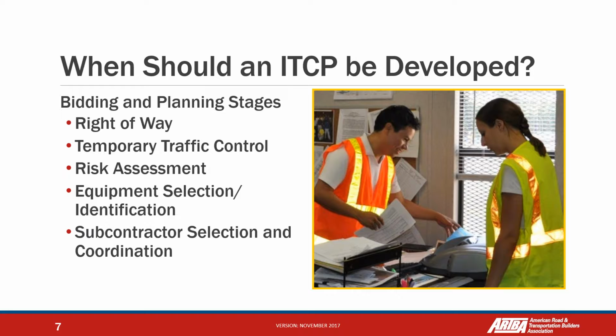Okay, we can talk about right of way, for example, all the space that we are going to provide for the project. How many lanes are we going to close? How are we going to do the temporary traffic control plan? The use of the MUTCD? Do we have the resources to put the signs, cones, barrels, jersey barriers, truck attenuators? It depends on the project, of course.